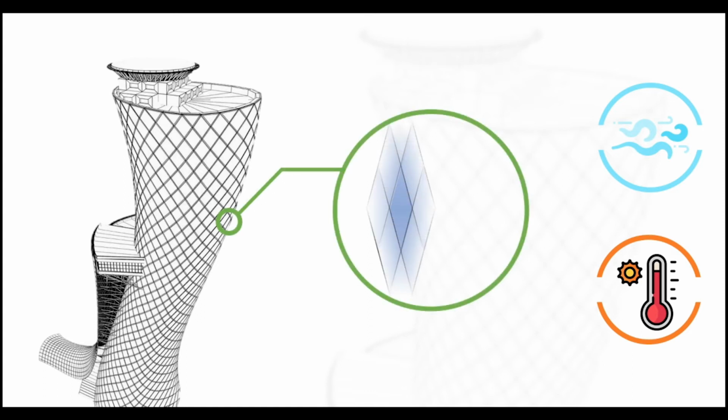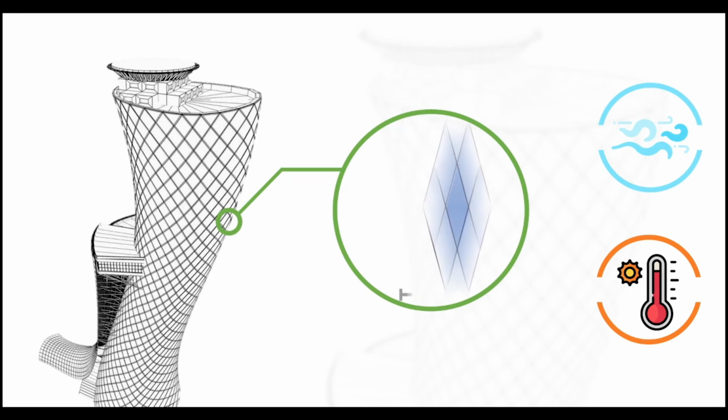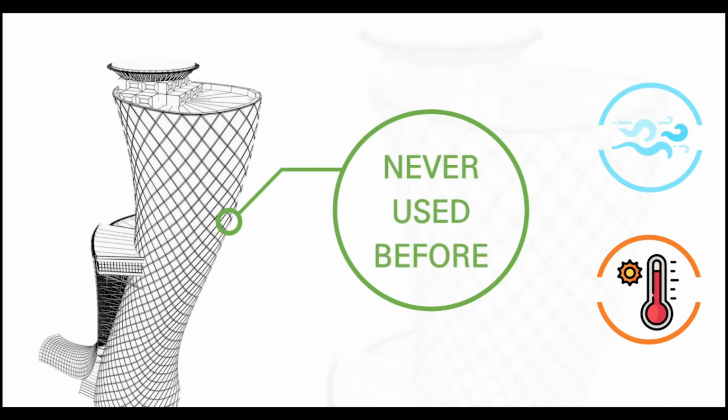Everything was pre-calculated through the 3D model, but to stop the glass shattering and keep the building watertight, the panels had to be designed to shift by up to 20 millimeters. Such a scale was never heard of in the normal skyscraper rulebook.